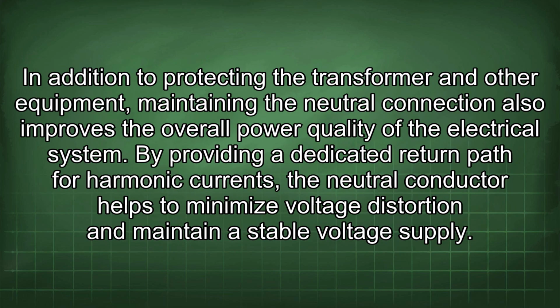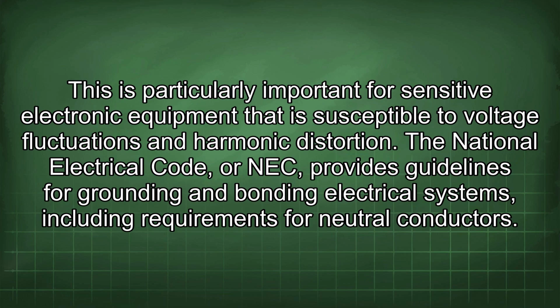In addition to protecting the transformer and other equipment, maintaining the neutral connection also improves the overall power quality of the electrical system. By providing a dedicated return path for harmonic currents, the neutral conductor helps to minimize voltage distortion and maintain a stable voltage supply. This is particularly important for sensitive electronic equipment that is susceptible to voltage fluctuations and harmonic distortion.